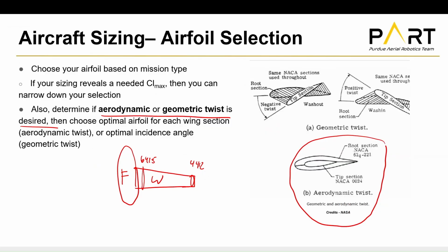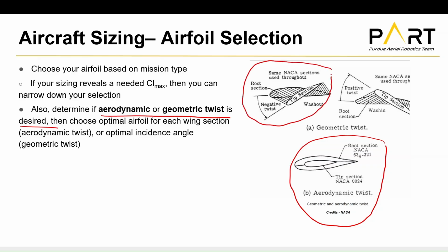If you wanted to reduce your wingtip vortices, which we'll get into, maybe you want a little bit less lift on your wingtip. As an example, that would actually work out quite well. Or you could do geometric twist, which is literally twisting your wing along the span of it. You can see that here. Washout is when you twist the wing tip down like this. See how it's twisted down relative to the root there. And then washin is where you actually tilt that up.